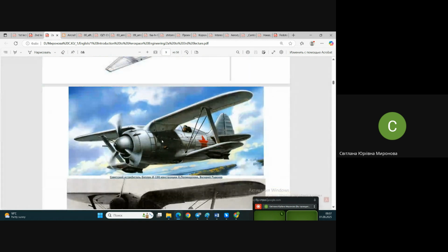All airplanes, especially military airplanes, should be compact. They must be as small as possible. It's the same rule working for other airplanes also: as compact as possible, if no other consideration takes place. Compact for what? The more compact the airplane, the less its overall size, the less extended on the sides, the less it will weigh with respect to the variant which is extended.